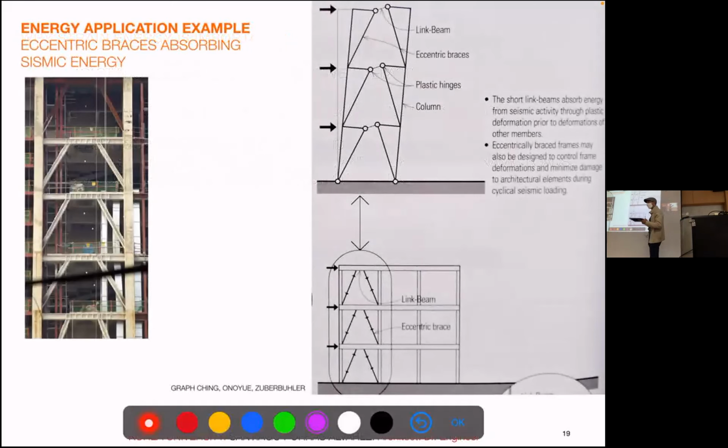And we will tell, if we have time today, I don't know, because I wanted to go fast, but we're not going fast. So we know that we have the bracings to absorb horizontal shakes, right? They should converge to one point to have a very rigid connection. This is a basic principle when you make a truss, right? But these are on purpose eccentric. So under huge loads, that will create eccentricity, and this point will go beyond the elastic limit. It will work in the plastic range. And we know that will absorb a lot of energy. So that energy will allow the building to stand that sudden shock.